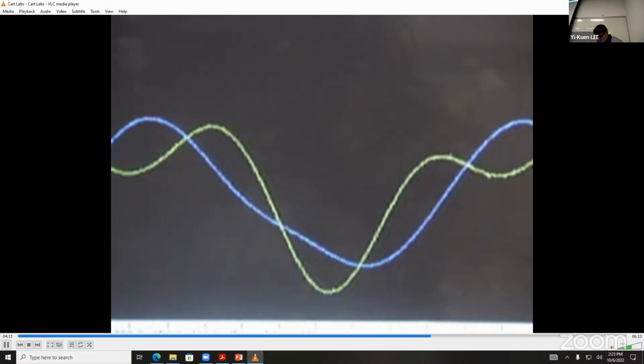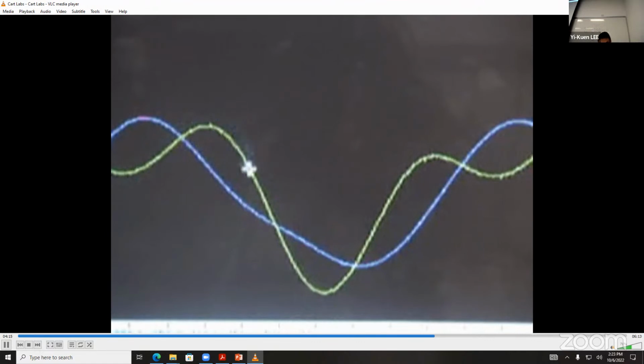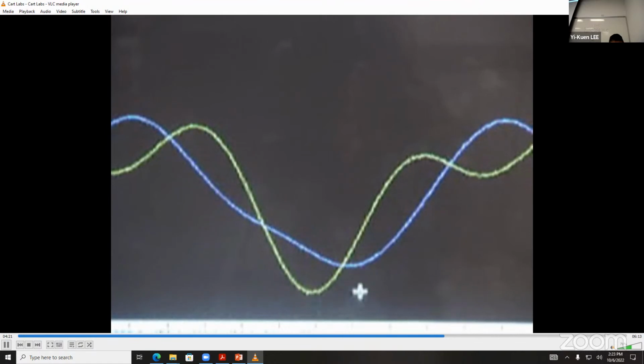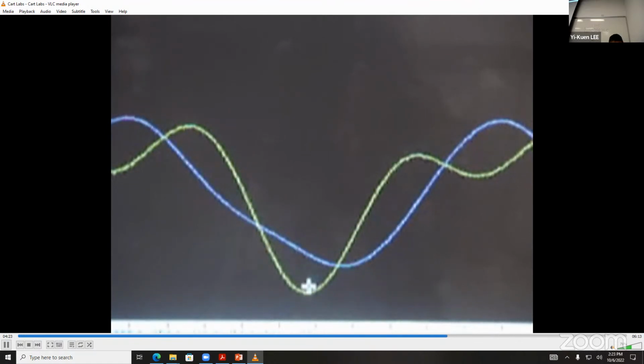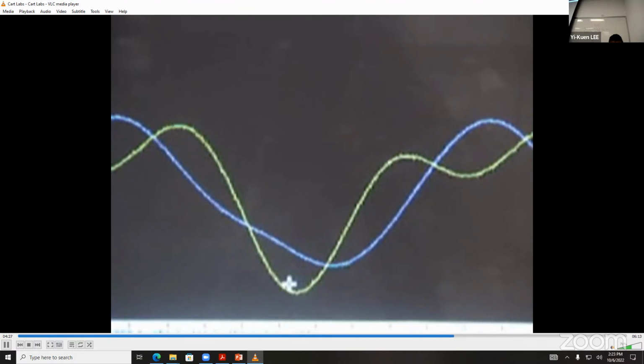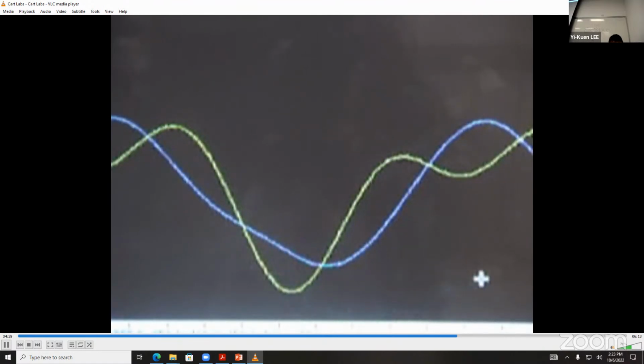And as you can see, we're exciting this higher harmonic, and we're getting oscillations at twice the frequency that the system's being driven. And also we have a slightly larger amplitude in the slider crank because we are experiencing resonance due to that higher harmonic.